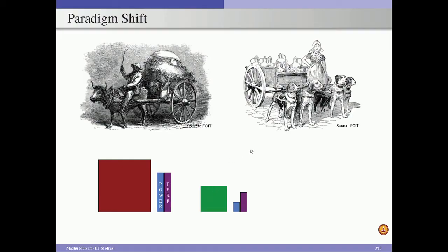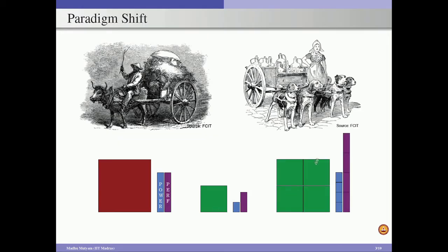Now, what we can do is replicate the simple core 4 times. As a result, we are taking the same amount of area as that of this complex core, and since each is consuming 1/4 of the total power consumed by this complex core, when we replicate this 4 times, we can clearly see our power consumption is almost the same as this, but the performance is improved. So, this actually gives us a motivation to go for multi-core systems rather than considering a single core system.